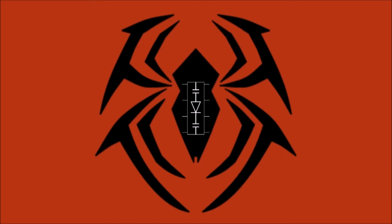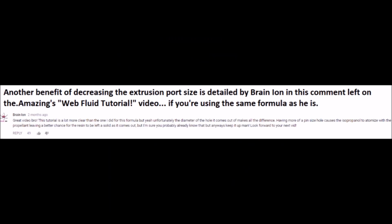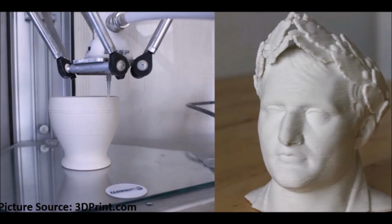For a formula that utilizes aeration, a larger main extrusion port may be necessary, probably with a diameter between 1/4 inch and 1/2 inch. If you're using a formula where you mix the propellant in with the fluid, try decreasing the size of the extrusion ports. This way, the overall decreased amount of pressure you're creating can be maximized by increasing the velocity of your webbing by putting it through these smaller holes. 3D printing allows us to create spinnerets to really any specification or size we want, and we're even able to create new mechanisms therein.